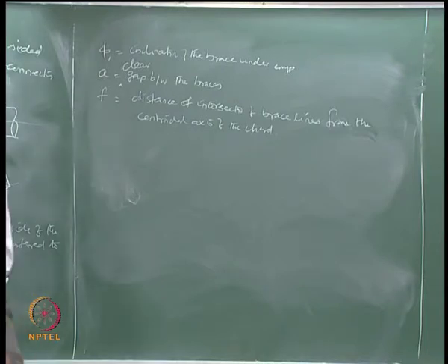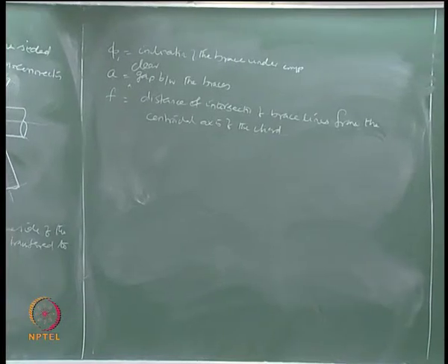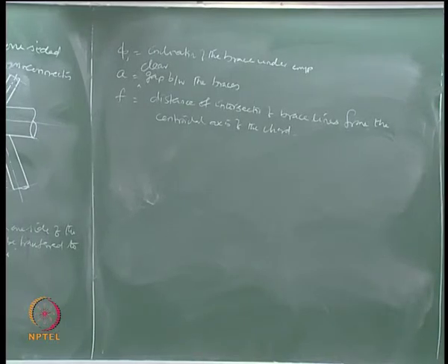So experiments conducted on this kind of joints, in case of one sided K joint, showed very clearly that the failure is essentially governed by the compressive force, okay.